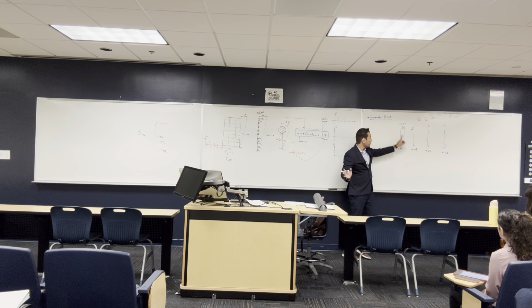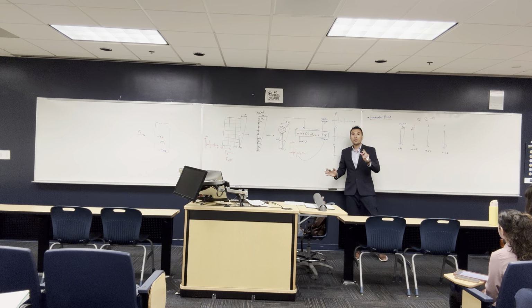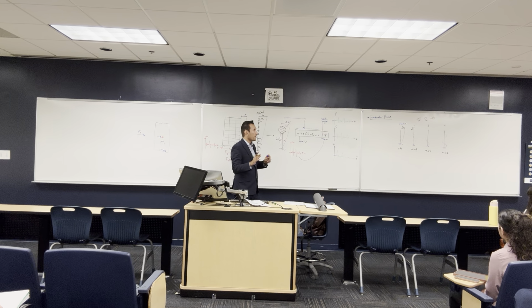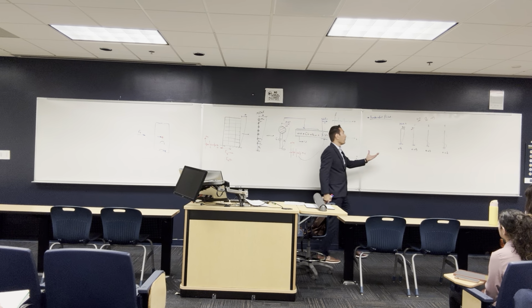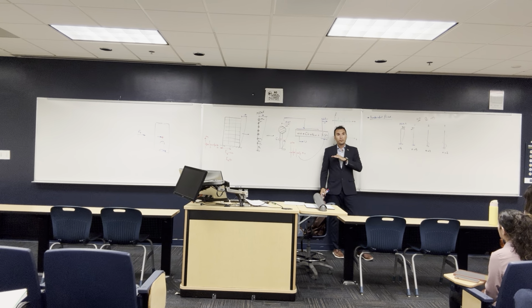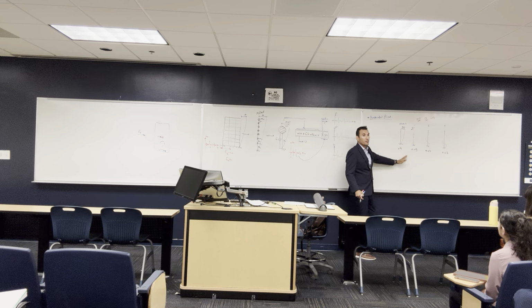So that's what I'm talking about, that everyone has a percentage. This percentage is called the participating mass ratio, okay? So that's why I'm telling you, for your record, there's a bunch of mode shapes. Usually when we do structural analysis for structures, mode shape number 1 is the main thing. Some codes say if the contribution of mode shape number 1 is over 90%, let's say you made your building perfectly symmetric and the contribution from the higher modes is very, very low, then maybe you can neglect that and assume that all the movement is moving with mode shape number 1.